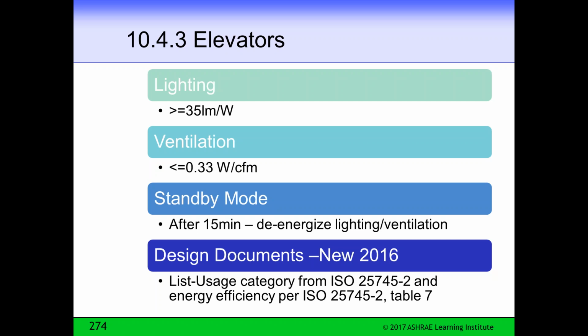Elevators. That's what I was going to say. One of the other reasons we went after plug load is because plug load is a big enemy to energy modeling and to meet LEED requirements or anything else. Because if you're saying I'm saving this much energy, what you do is you say that the total energy of the building is divided in your savings between your baseline building and your new building or savings, and then you divide by usually the total energy used in the baseline building, and that includes plug loads, and plug loads includes all miscellaneous loads and all deregulated loads.